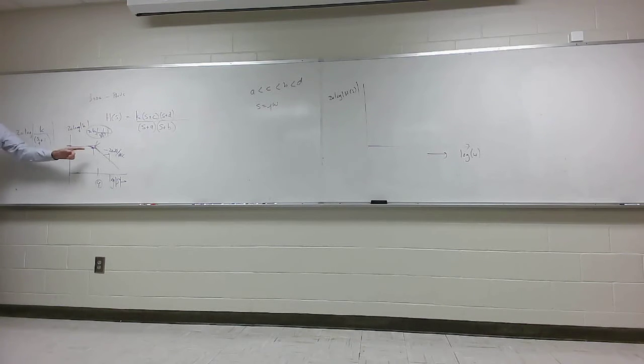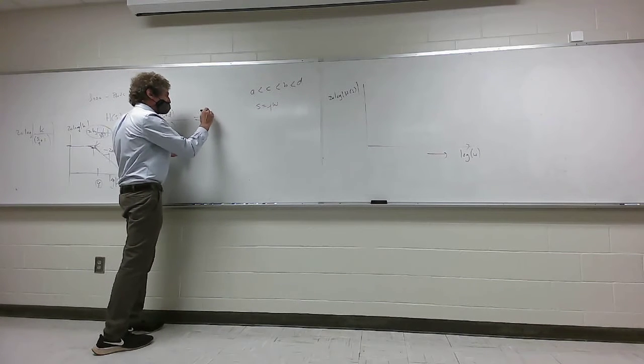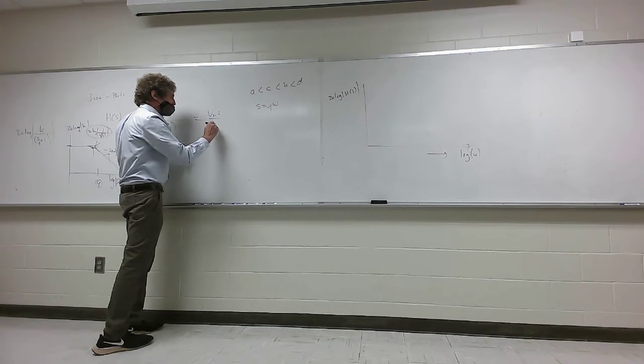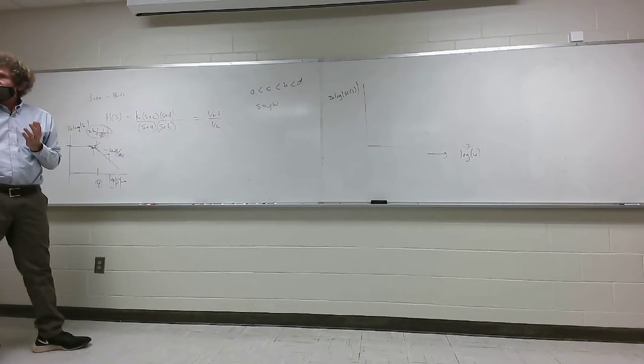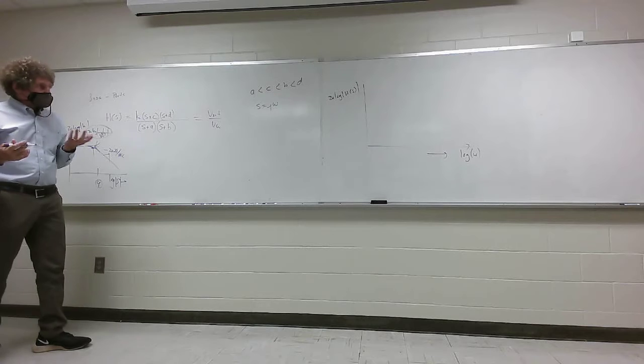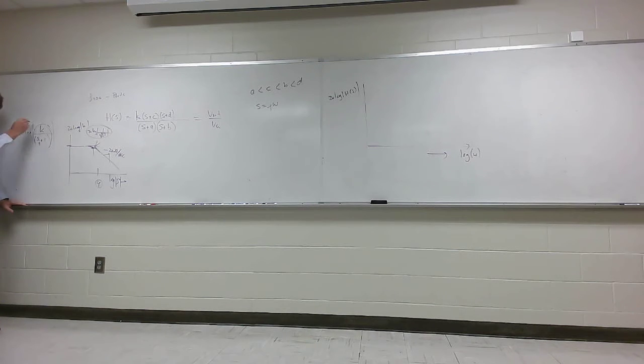Now, some people don't understand this. The reason is, we're assuming this transfer function is a ratio of voltages or currents. A typical transfer function would be something like V out over V in. Y'all with me? Transfer function, relationship between output and input. Well, the reason we say 20 dB per decade is because if we look at this value and we go over 1 decade of change of frequencies.